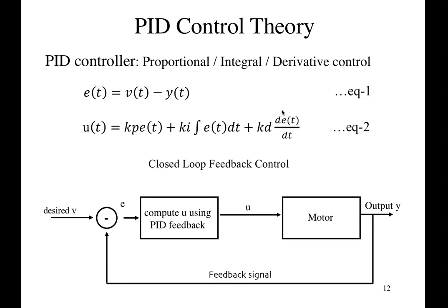But it all depends on your application, and you have at least three parameters to select. You can set them to 0, which will make that term disappear. But if you want to use that term, then you have to select decent values. There are a number of ways we can select these values. This is what we will discuss during this module: how to design control gains and select the control structures.